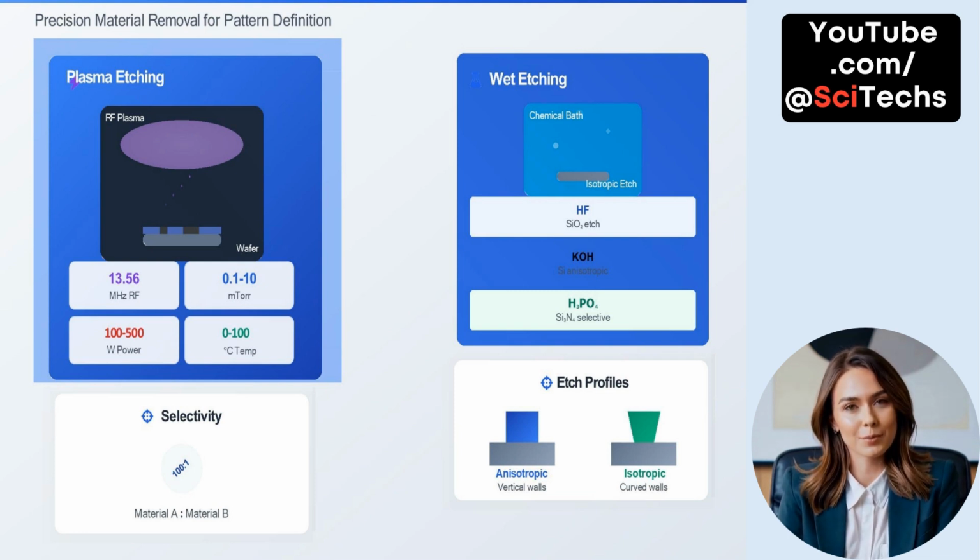The power applied ranges from 100 to 500 watts, while temperatures are controlled between 0 to 100 degrees Celsius. Plasma etching offers excellent selectivity, up to 100:1, meaning it can etch one material much faster than another. This enables fine patterning with vertical sidewalls, called anisotropic etching.